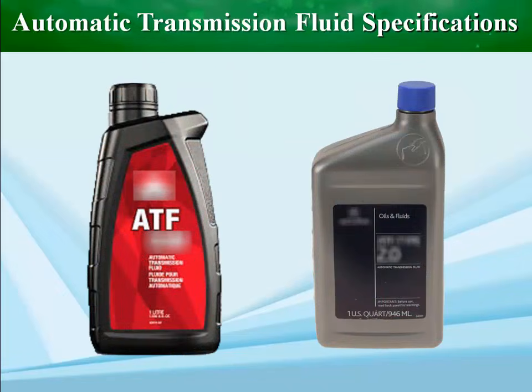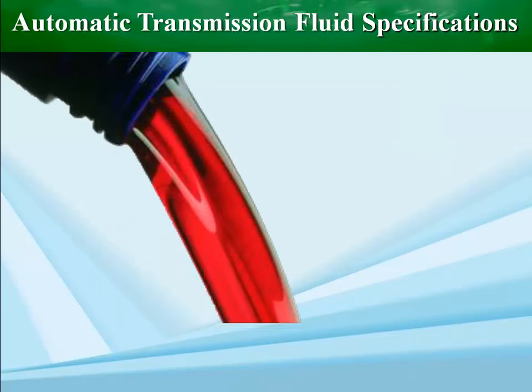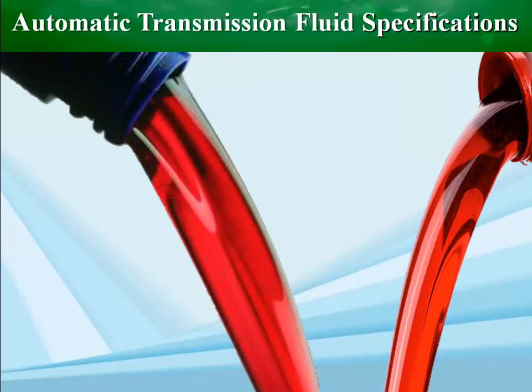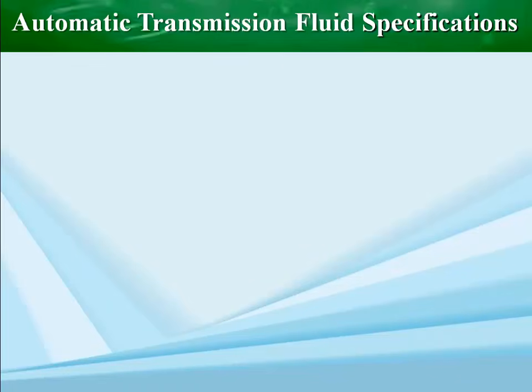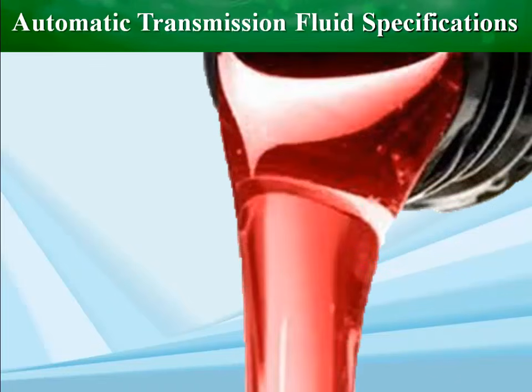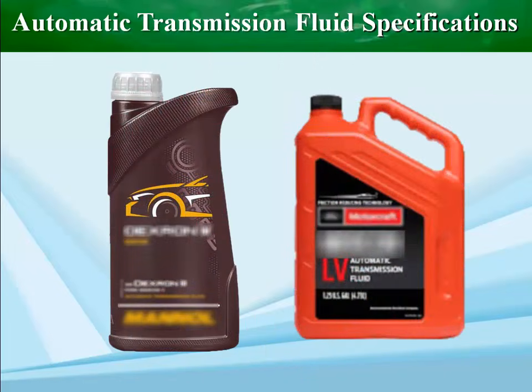ATF is a specialized lubricant. It is not an oil but rather a mixture of various chemical compounds with a significant number of additives. It must meet many specifications. ATFs are colored red to distinguish them from other liquids used in a vehicle. ATFs are specified mainly according to vehicle manufacturers' directives. Common ones are Dexron, General Motors, or Mercon, Ford.